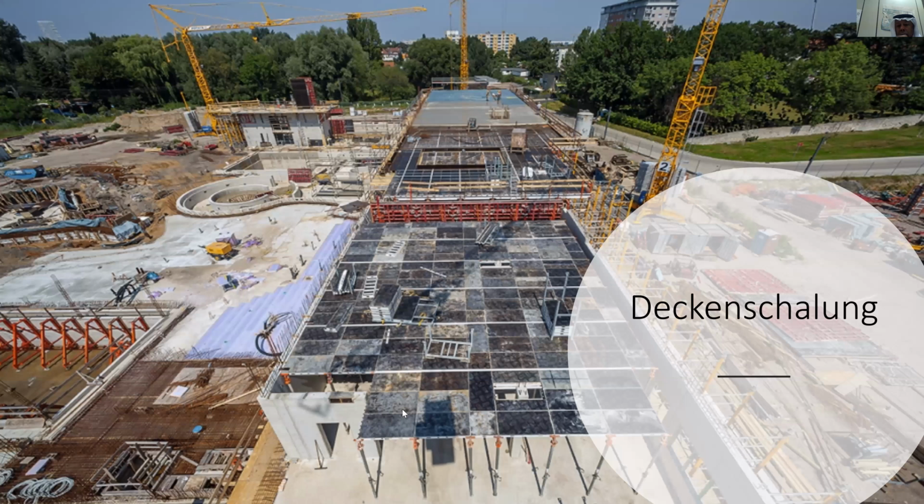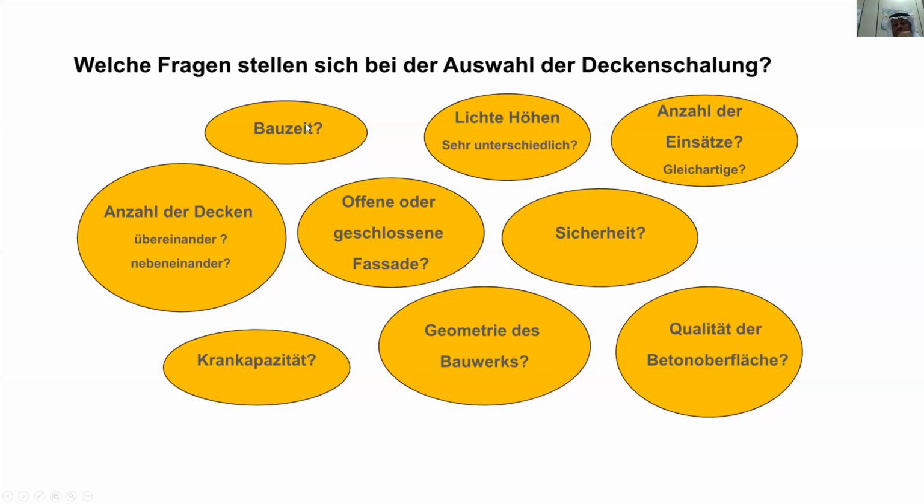So I have to think what's in this case for this project, what's the timing of the project? How much time have I got? Then it's the number of slabs. Do I have parts? What kind of cranes do I have? What's the capacity of the crane? What's the geometry of the building?